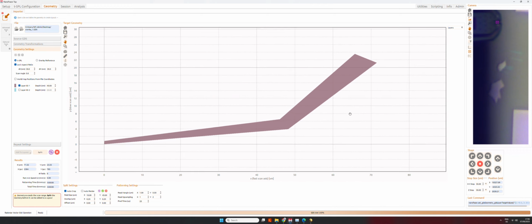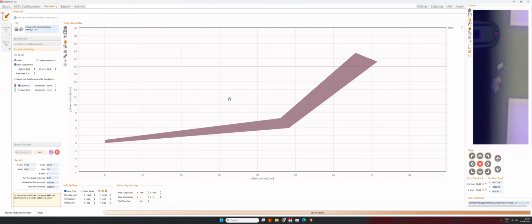So what we recommend is trying to do a test pattern somewhere. In this case, when we're contacting over flakes or nanowires, we always do 2D lithographies. So we will find a good value for the force through the feedback, and then we will use this value of the force, with a specific value of temperature and forward height, to pattern our structure. In this case we put 40 nanometers depth, but we don't really care that much.